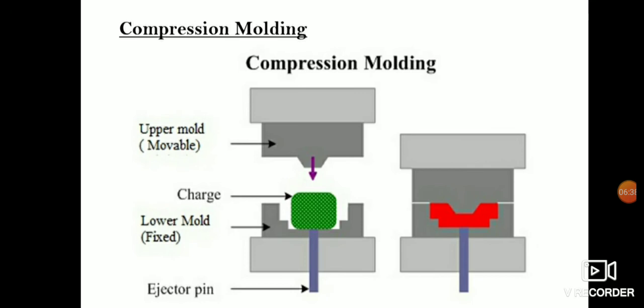The next one is compression blow molding. Compression molding is among the oldest thermoset materials processing techniques. Fundamentally, a compression molding device is a vise-like press that heats, hence it is also known as a heated press. A compression press is rated by its capacity or maximum force.